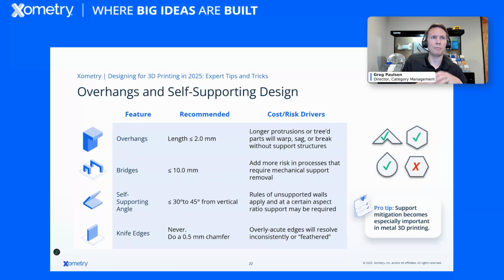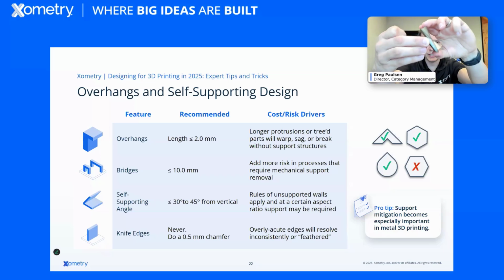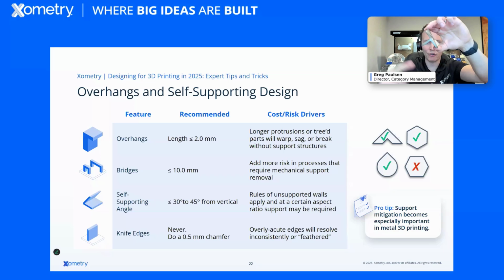So when we talk about features, the other thing we need to consider is that support structure, right? So we've been talking about growing parts, near net shapes, and support structure. I can build features on a design that do not require support. This is something where usually using a 45-degree angle will help out a lot. So I have, for example, a little kickstand design here. Just notice that it's a bunch of 45 triangles. So I have these features building off naturally.